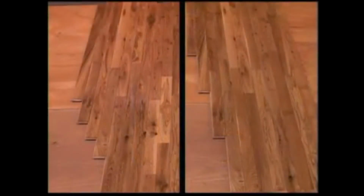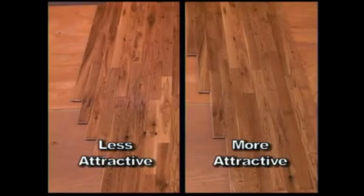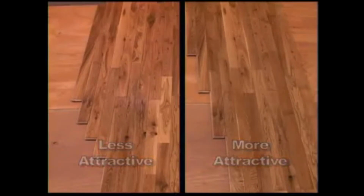Remember that all hardwood flooring installations are a series of end cuts at the beginning and ending of each row. Plan ahead. Know which boards to cut, where to cut them, and where to place them. This will allow a much greater yield from the carton and minimize waste. Usually, 25 to 50% of the boards in a carton will be cut to a shorter length for an average job. Selective cutting is expected and produces a better appearing floor, less waste, and is easier to install.